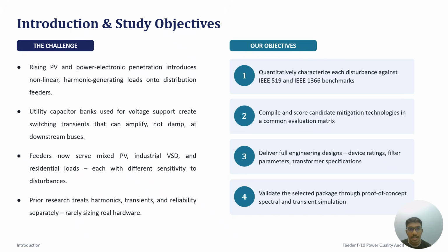So the gaps define four objectives: to quantitatively characterize each disturbance against IEEE 519 and IEEE 1366 benchmarks, compile and score candidate mitigation technologies in one common evaluation matrix, deliver a full engineering design with real device ratings and filter parameters, and finally validate the selected package through proof of concept simulation.